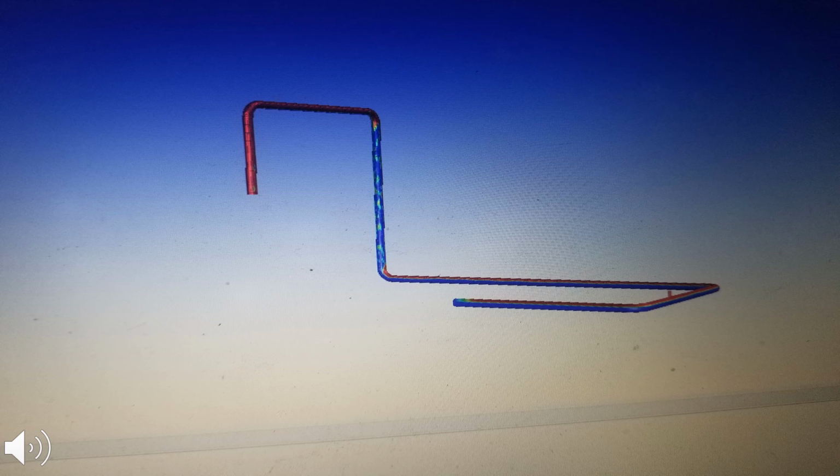We used the time discretization of 0.001 seconds and recorded the data every tenth of a second. Here's a graphic of the phase contours at 14 seconds, which showed us we need to partition the riser before simulating if we want to later create animations with the view inside.